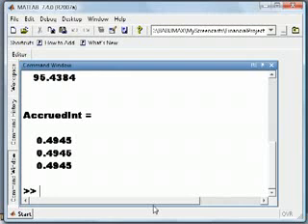Now we will convert this algorithm to a .NET assembly. MATLAB provides an inbuilt tool for this, so we don't have to worry about how the marshalling will take place and all these things. This can be done very quickly, and we can convert our algorithms to .NET assemblies with the help of the .NET deploy tool.